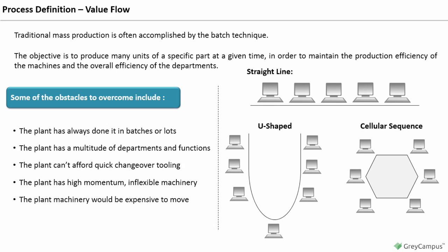When the machinery is performing as expected, there are zero breakdowns. This is the concept of TPM, or total productive maintenance. The quality level of each operation is very high, near perfect, using a variety of defect elimination and detection techniques. The activities needed for production should be in a steady, continuous flow, with no wasted motions, no batches, and no WIP. There should be flexibility to meet the present needs. The work of people, functions, departments, and firms will require adjustments to the value stream to make it flow and to create value for the customer.